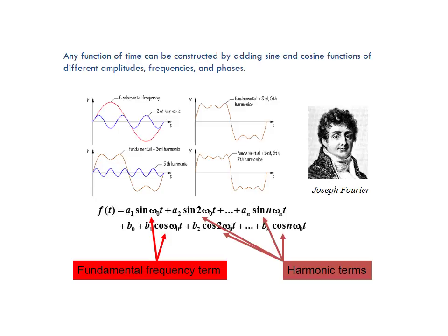So anyway, we have our 5th harmonic plus our 3rd harmonic plus our fundamental frequency, because we're taking the output and adding another 5th harmonic. If we look at that, we're going to get an even more square wave. So the more signals and harmonics that we add on, the more square it's going to become. Eventually, you can approximate a square wave close to infinity by doing it this way, which is exactly one of the ways that we can approach a square wave.